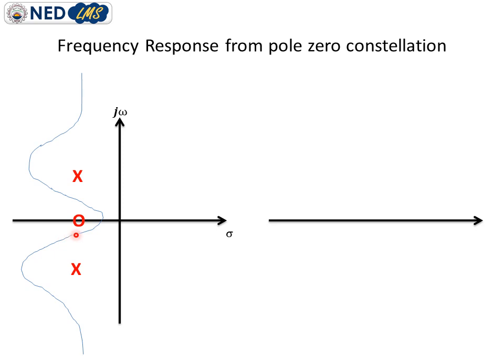But as soon as it reduces to the normalized value, it encounters a zero along its walking track. So the response is shifted or attenuated below the normalized line because of this zero. So when exactly this zero is encountered, the gain attenuates to its maximum value.